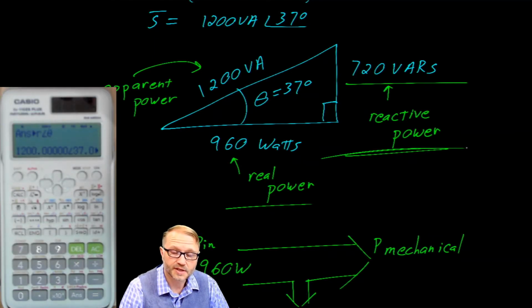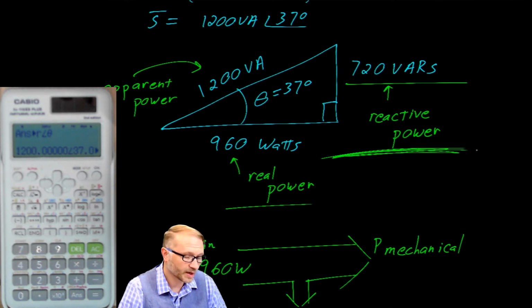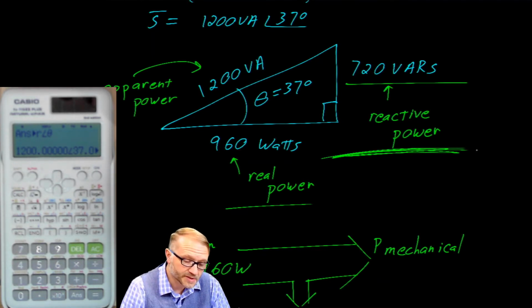Actually, we should move that statement back just a little bit, because when we're talking about reactive power, we're talking about the energy that's stored in the magnetic field. And when we get to motors, you'll see that it's the magnetic field that actually allows the motor to function. So you could argue that without reactive power, there would be no magnetic field. Without a magnetic field, there would be no motor.